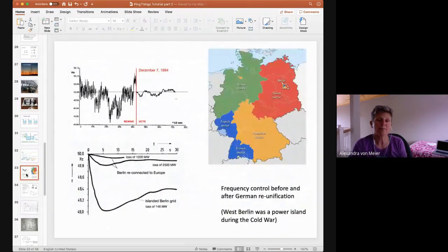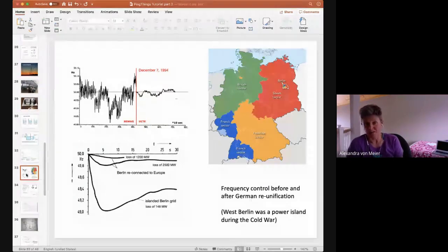So depending on which plants are online at any given time performing frequency regulation, you'll see the frequency be more or less jittery. And then depending on whether weird stuff happens with the load. I think a big test is going to be whether advanced inverter controls can be implemented soon enough that they can demonstrate improvement in the frequency response, as opposed to being a drag on the system and making life harder for the grown-ups.